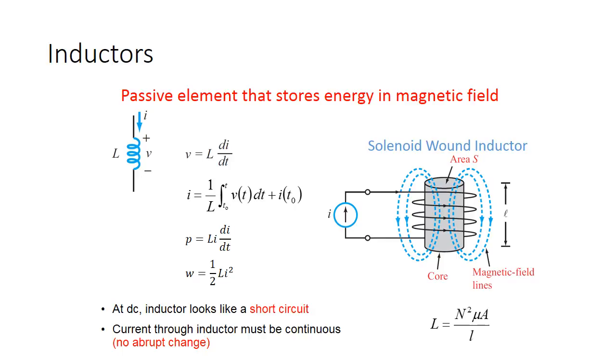So we also have another piece of electrical technology at our disposal called inductors. And inductors are shown by this symbol on the left, which is like a squiggly line that swirls down. We have a voltage drop over the inductor. We have current going through the inductor. And for inductors we use L to represent, and they're in the unit of henries. So the voltage equals L, which is how many henries the inductor is, times di/dt, or the change in current over the change in time.